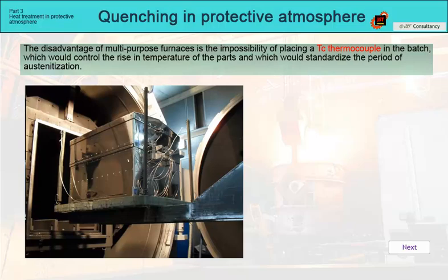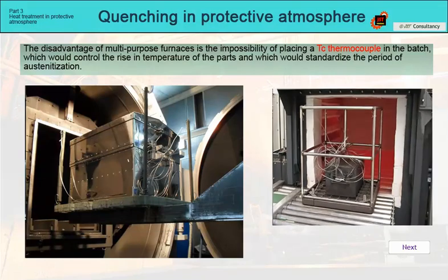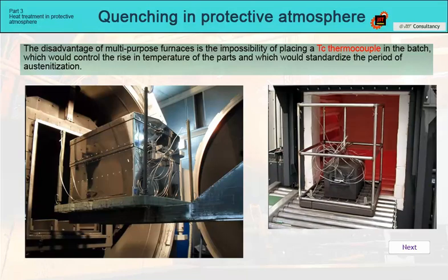However, this is an interesting option for modeling the heat treatment process with respect to the batch in the case of repeated production, and the main criterion is the economy of the process. In this case, we need the data logger's protective box to protect the device during a 3 to 4 hour cycle at a temperature. However, we will definitely use this device to measure the temperature uniformity in the furnace, to classify the furnace into the accuracy class, according to CQI-9 or AMS 2750, in the periodicity, according to these standards.